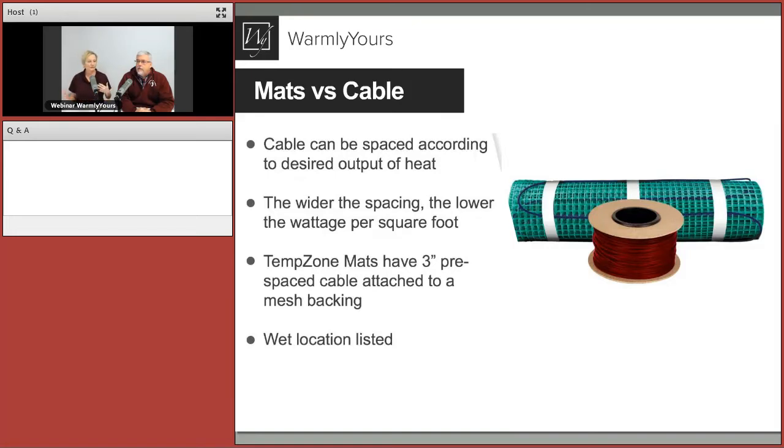And in the number of years that we've been doing this, 20 for me, over a decade for Scott, that just doesn't make sense to us, because with electric floor heating, you can actually control the temperature to a greater degree than you can hydronic systems. Hydronic systems can swing. Overshoot. Okay, overshoot, and so they can overheat and then underheat. So just to encapsulate what you said there, what happens with hot water heat is if you ask it to be at 80 degrees, when it comes out of the boiler, it's going to be 85. So your floor is really going 85.